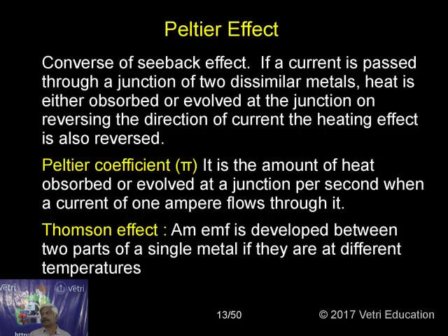From this, what is the Peltier coefficient? The Peltier coefficient is just like the Seebeck coefficient. It is the amount of heat energy absorbed or evolved at a junction per second when a current of 1 ampere is flowing through it. The Peltier coefficient unit is volt. So here also we have to find out the Peltier coefficient.